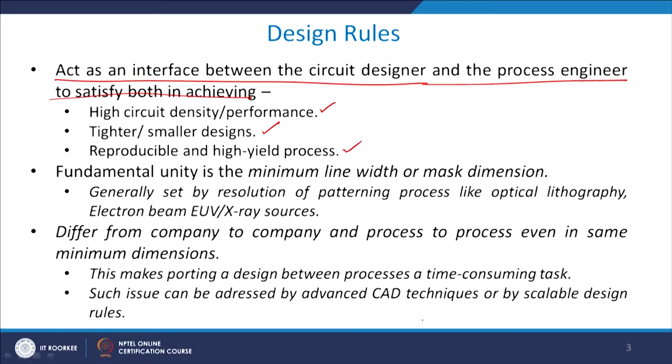So, this is sort of a talking point between the circuit designer and the process engineer, and therefore, if a circuit designer follows these rules very thoroughly, then chances are that his design will be accepted by the process engineer and he will be able to send it for proper fabrication. If not, then he has to iterate back to the circuit designer to change his design rules.